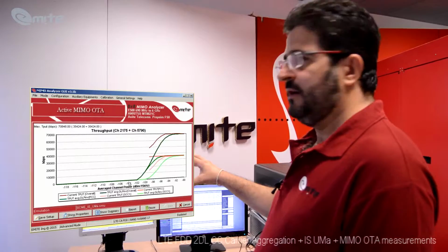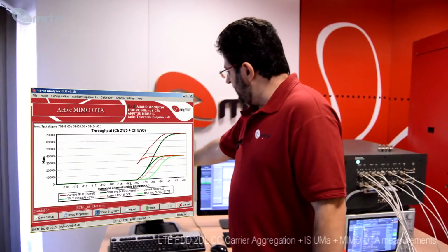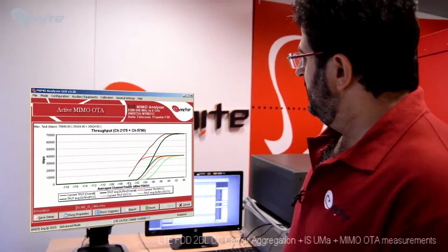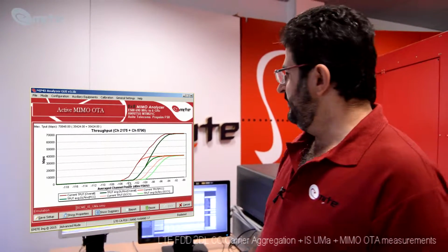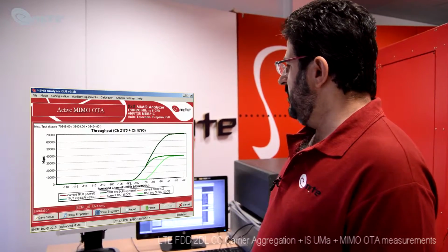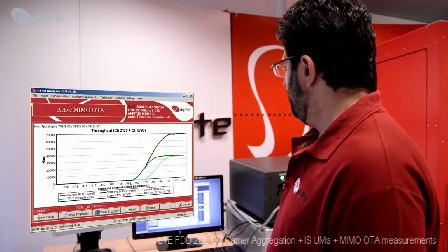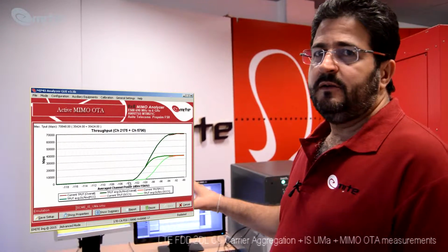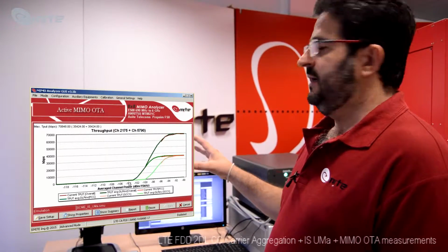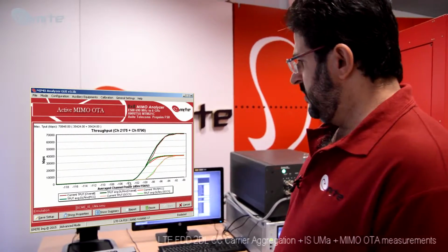So all 3 components are being measured, and they evolve in time, and to get a sample curve, and that sample curve is averaged with the existing ones to get the final curves for the measurement. Now this will go for something like 5 to 7 minutes for this measurement to run, and until you get all the curves, you will not get the accurate result. So you have to get all the samples measured and then average them out to get the accurate results using the reverberation chamber.